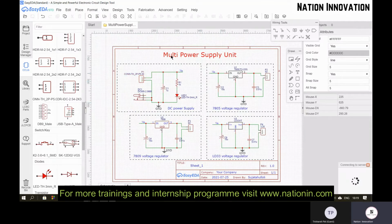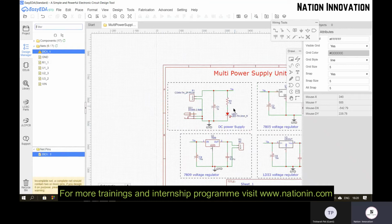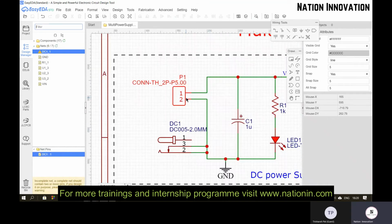Okay. So save the schematic and go to design, convert the schematic to PCB. It's showing like there are some unfinished nets. Let me check. Okay, I missed one connection here.